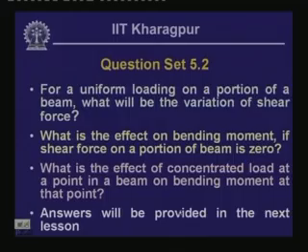Now, some questions are set for you: for a uniform loading on a portion of a beam, what will be the variation of shear force, and what is the effect on bending moment if shear force on a portion of a beam is 0, and what is the effect of concentrated load at a point in a beam on bending moment at that point.